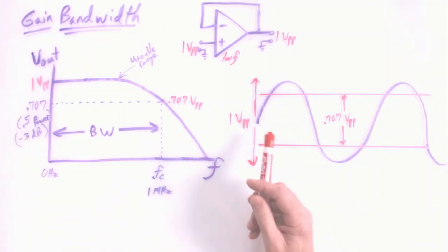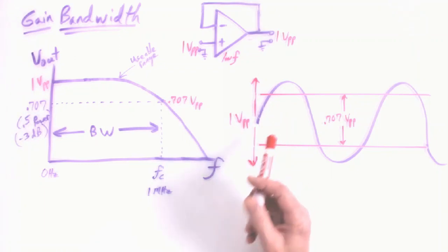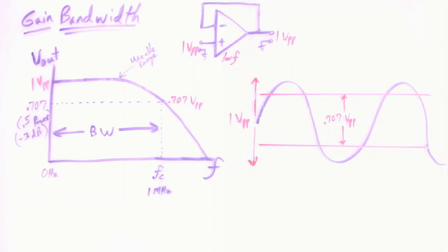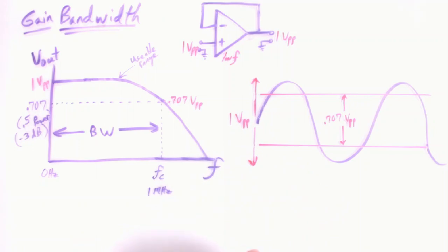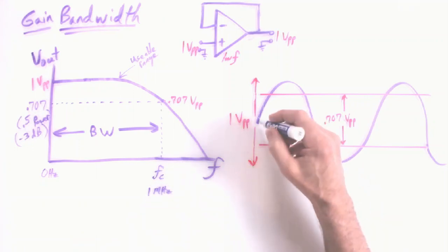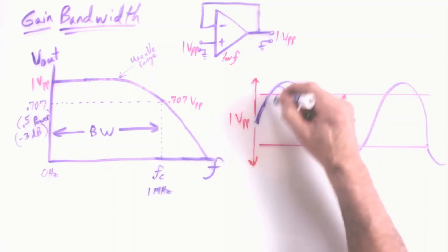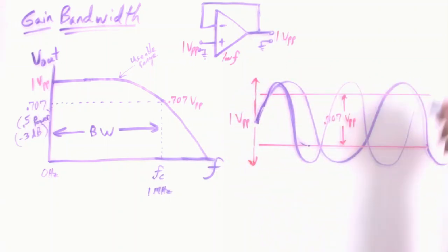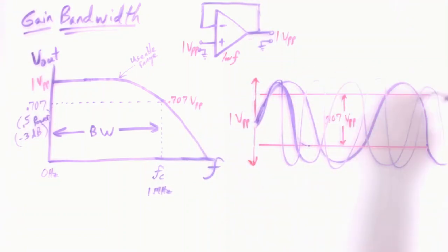So with this setup, you're all ready to go. You've got your 1 volt peak to peak up on your scope screen. Again, nothing like the Bode plot looking like that. Now all you have remaining to do is crank up the frequency of your input signal, and watch what happens. So you'll start to increase the frequency, and it's going to maintain the 1 volt peak to peak. It's going to get pretty busy here, right?